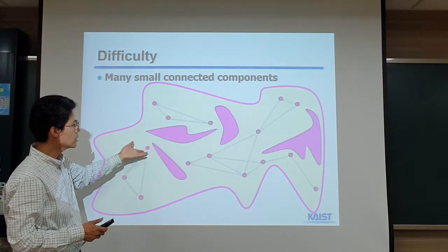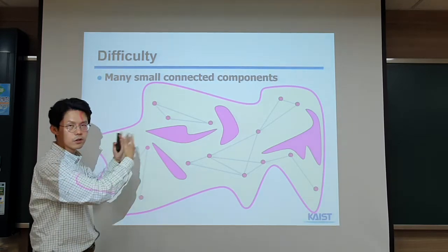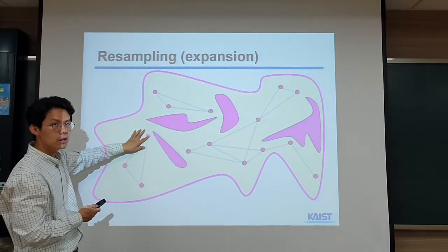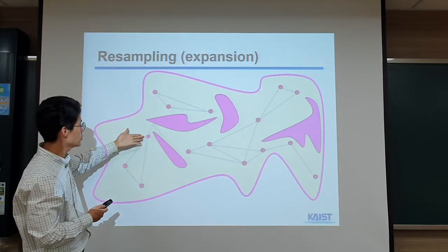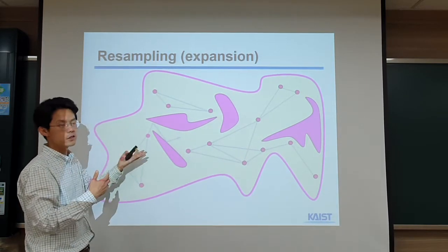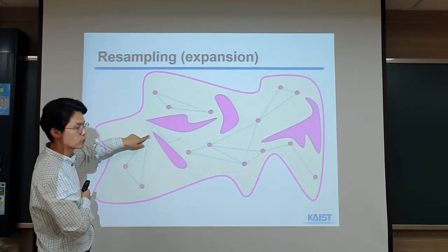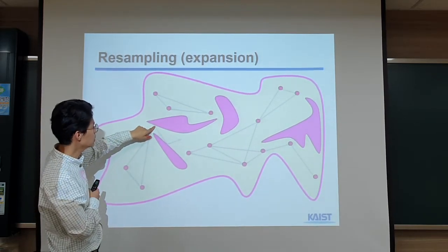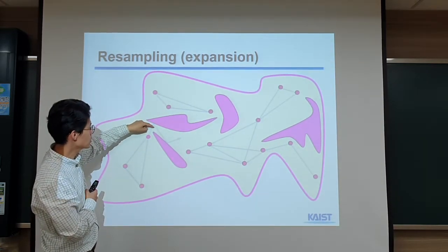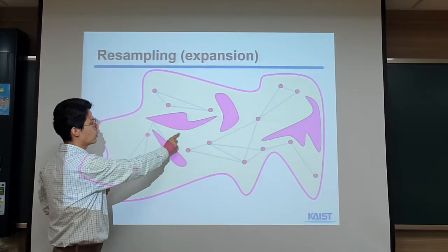And then for that region, given this small region, we can do some sort of uniform sampling. But another idea is that for that difficult region, we do some sort of shooting. So for example, instead of generating a random sample and trying to connect it, we already know that it's a very difficult region, right? So instead, we can pick a random direction and walk along that direction. If we hit a collision there, we randomly change direction, and we keep doing that, right? And then at that point, we generate another node there.